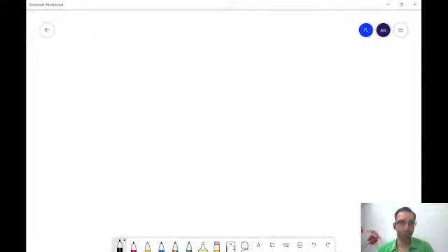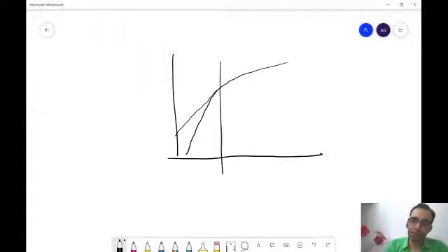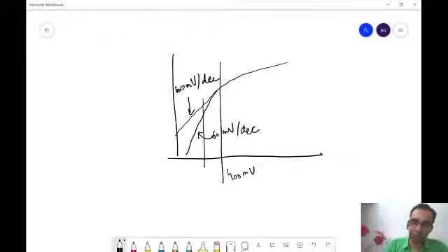Yes, sir. So what we are saying is, there is this curve, and there is a curve where the slope is like this. I said that let the threshold voltage be 400 millivolts. This is, let us say, 60 millivolts per decade. This is, let us say, 100 millivolts per decade. Now, let us say I am at 340. My gate is at 340 millivolts.